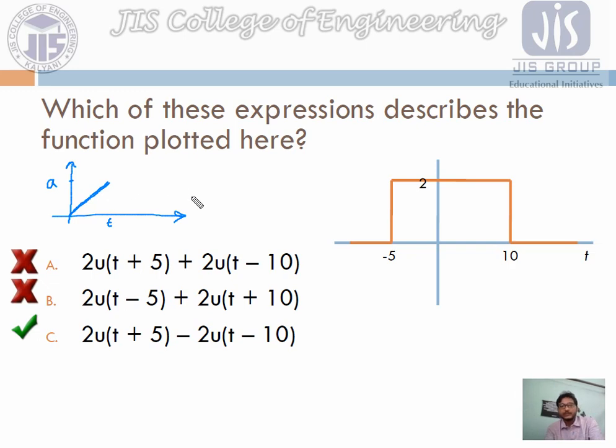Previously for the step signal we have seen that throughout the time we have defined, the step value is fixed, or if the step value changes at a certain time, then again it will be fixed or constant. Now for the ramp function its amplitude is gradually increasing. So what will be the mathematical equation for this ramp function? Obviously for this straight line or increasing function we can write a into t, and the ramp function is denoted as a r